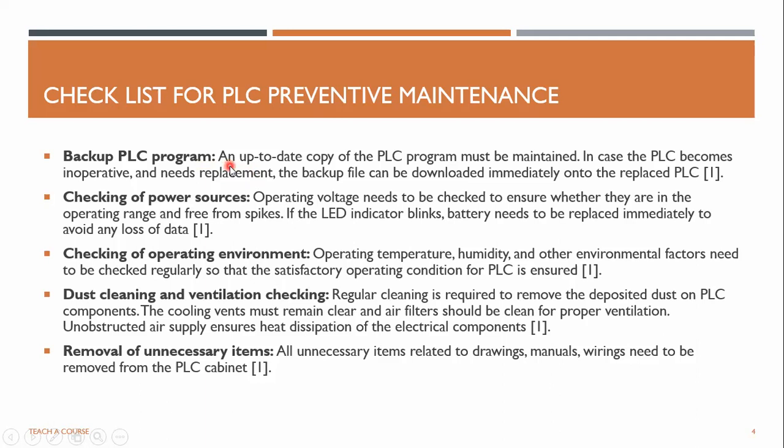So you have to have an up-to-date copy of the PLC program, stored somewhere separately. So in the case the PLC becomes inoperative, like if the PLC is damaged and needs to be replaced, your backup file can just be downloaded to the new PLC. Otherwise, you will end up with a massive problem.